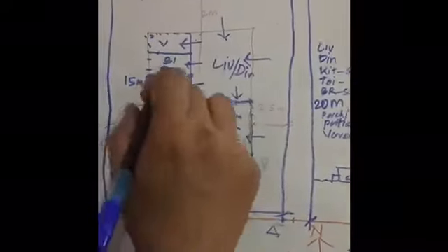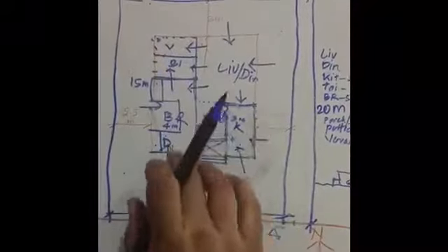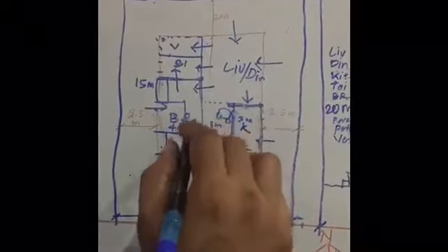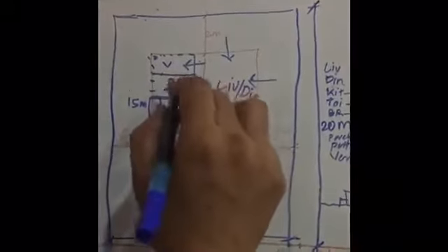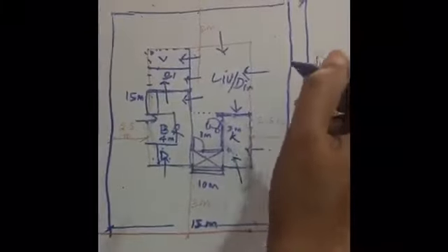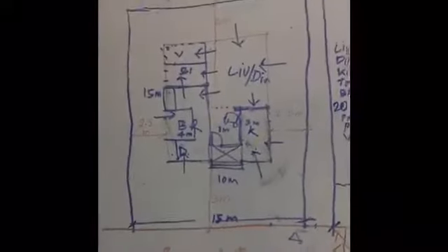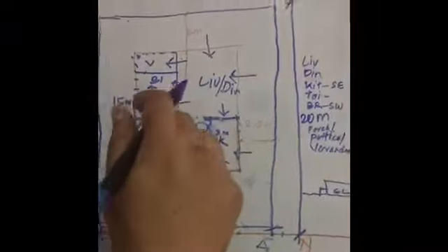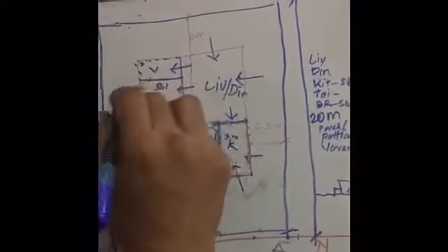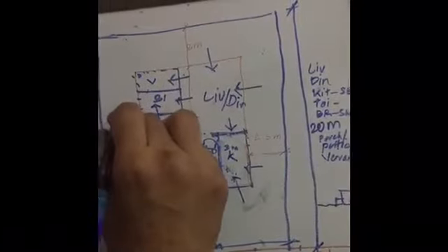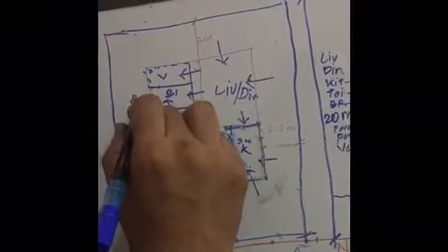In this 15 meters, you just have a veranda, you have a bathroom and a bedroom. So you get a very giant bedroom here. So you can distribute, if I say, I'm not sure, a bathroom cannot be, you can't have a huge bathroom unless you are having a bathtub and a shower and WC and 2 wash basins. Unless you really need it, the bathrooms are not so giant. So you can restrict the bathroom size, the width of it, to about 2 meters. 2 meters, about 8 feet. That's giant too.